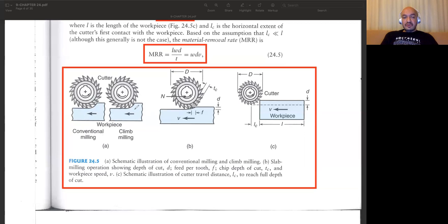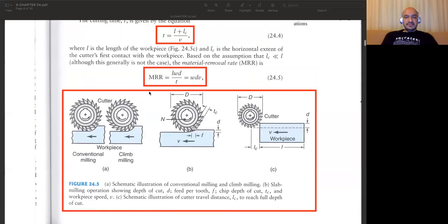And it's highly important, actually, in climb milling. If you cannot eliminate backlash in the underneath mechanism of your table, then you will have problems in the positioning of your table, more in the climb milling. But it's not a big issue in the conventional milling. Even though you have some amount of backlash, that will not be a big problem in the conventional milling operations.